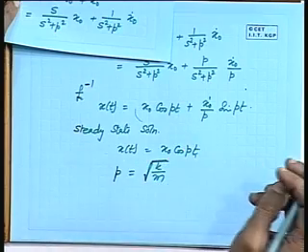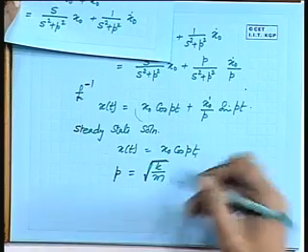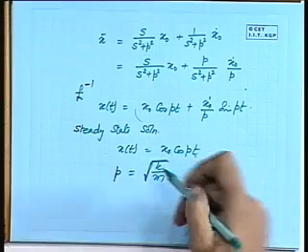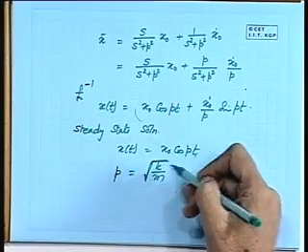So we can get the frequency of the same thing, no? It is the same thing. Whether it is sine curve or cos curve, it is only a shift of pi by 2, pi radian. Okay. So, this has got a circular frequency given by square root of k by m. Now, from this we can find out that frequency is governed by the stiffness and mass.